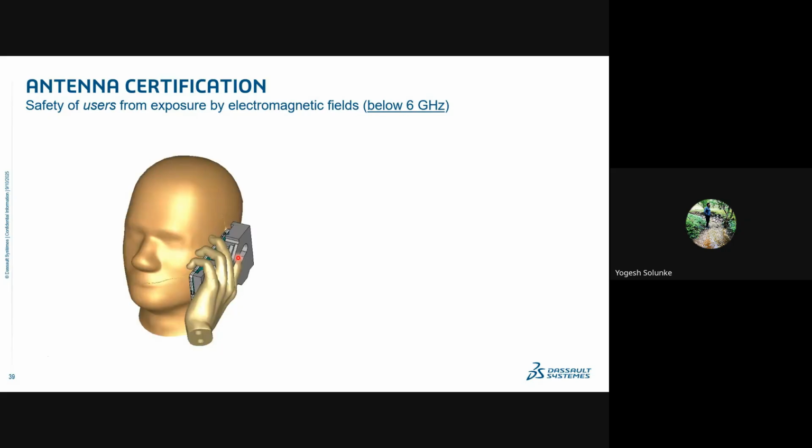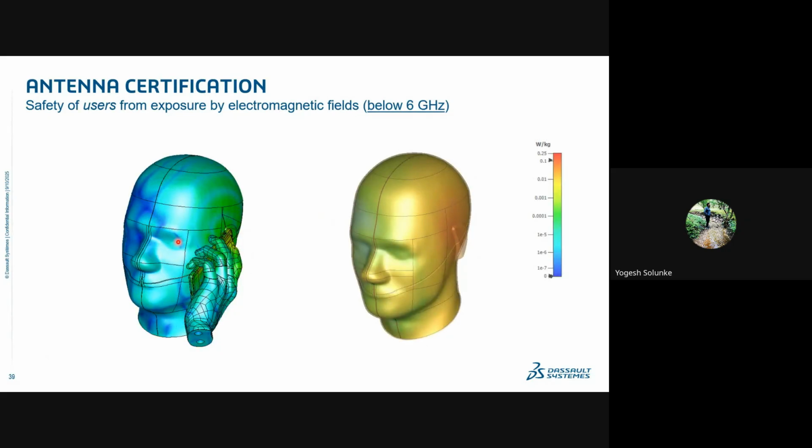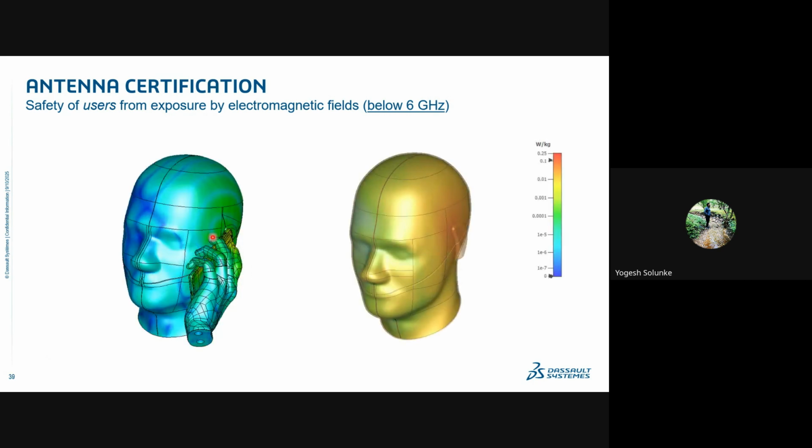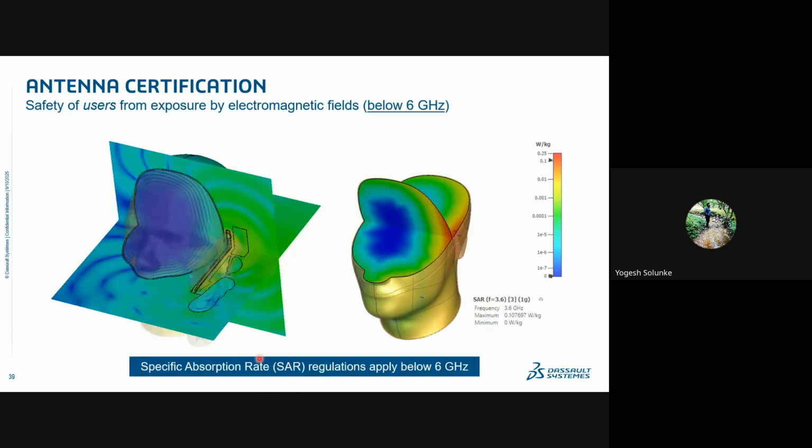In the safety case, again, at the end, for those working on biomedical applications, if you have an antenna designed at a particular frequency, once you keep it inside a mobile phone near the head using phantoms or any voxel data, we can see how it behaves. Once you excite it, you can see how the electromagnetic field travels. Mostly we do SAR simulation, which is specific absorption rate. Here you can see how much SAR there is at your resonating band. We have some standard limit value for that, so to pass certification, we should have that SAR value be minimal.